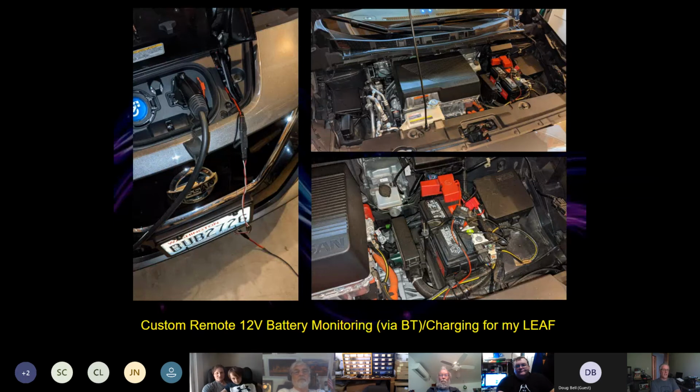the dealer had to keep the car overnight and put it on his own charger to prove to himself what I was telling him: one of the cells died. The battery would drop immediately from 12 volts to 10 volts if you put any kind of load on it. I said, well, one of the 2-volt cells has failed on this. They said, well, we've got to check it with our equipment and be sure. And guess what? It was exactly the problem. They put a new battery in it and things are fine.